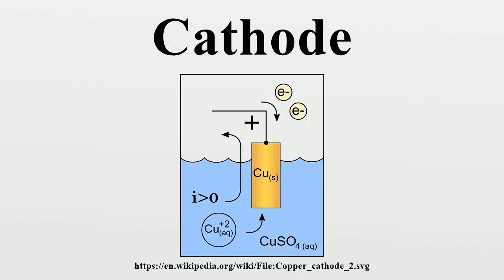Cold cathode. This is a cathode that is not heated by a filament. They may emit electrons by field electron emission, and in gas-filled tubes by secondary emission. Some examples are electrodes in neon lights, cold cathode fluorescent lamps used as backlights in laptops, thyratron tubes, and Crookes tubes. They do not necessarily operate at room temperature.